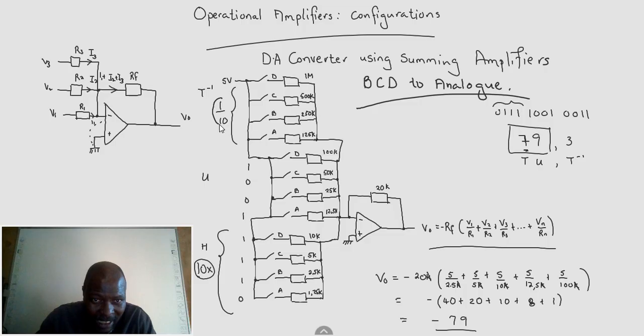The factors of the currents are going to increase or decrease according to whether you are going bigger or higher. Remember, conversely, if the currents are going smaller, it means the resistors are going higher, bigger, all right? So now you see that this is another set of 4 bits, and you say you want 0, 0, 0, 1, 1. Remember, the smallest resistor gives us the most significant bit.